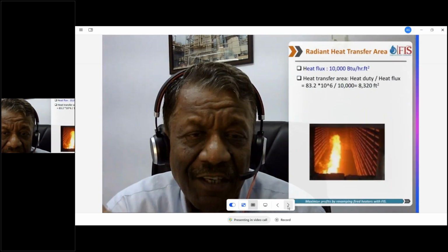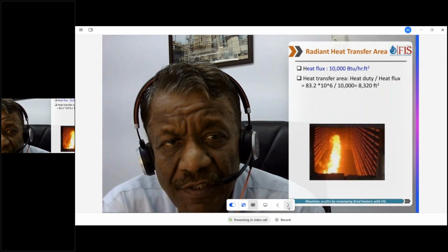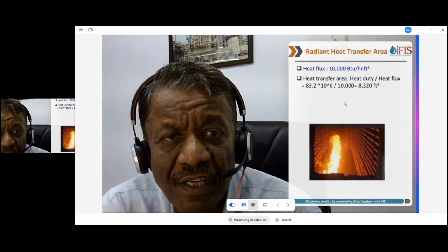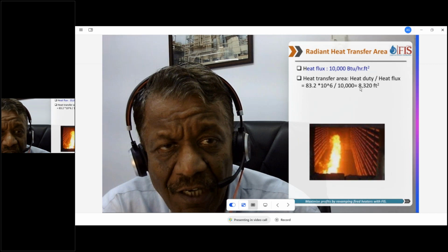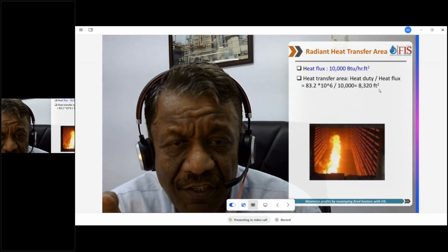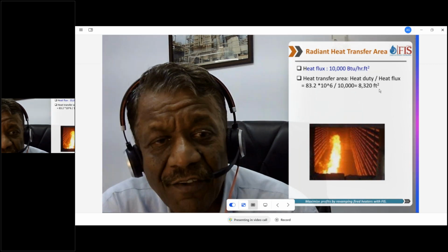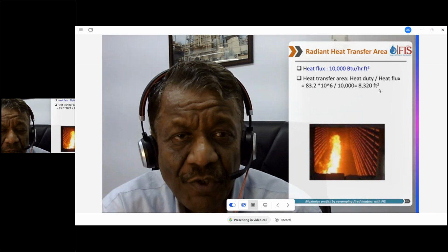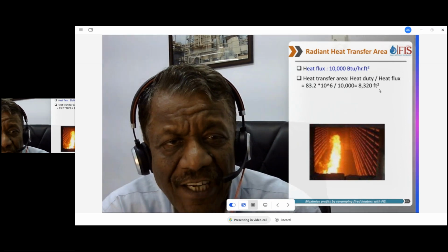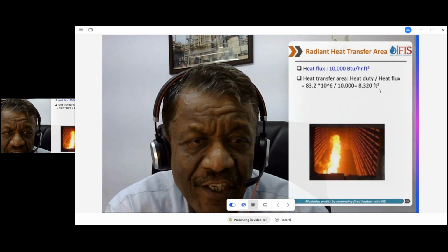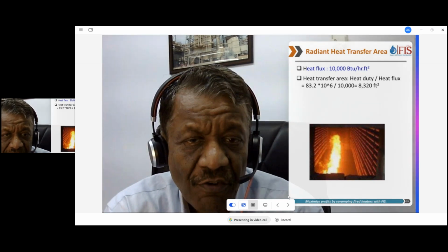Then we selected a heat flux of 10,000. Once we select a heat flux, we know how much surface we have to provide. We take the radiant heat duty divided by 10,000, which is 8,320 square feet. Very simple calculation. We are not doing hi-fi calculations as yet, just simple arithmetic. So we need to provide about 8,400 square feet of heat transfer area for this radiant section. Let us see how we can provide that surface.